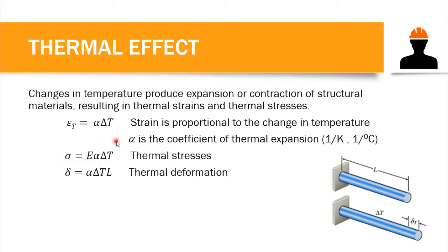Then for the thermal stress, the stress is equal to the modulus of elasticity times the strain, correct? That is our stress. And the value of strain is alpha times the change in temperature. So that is the thermal stress.